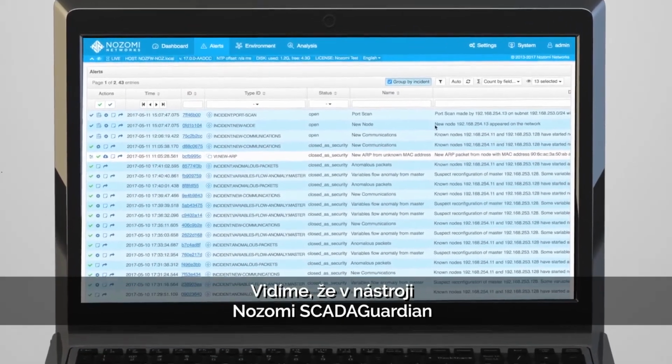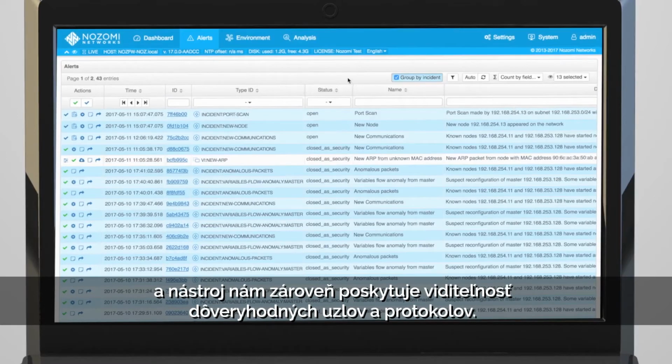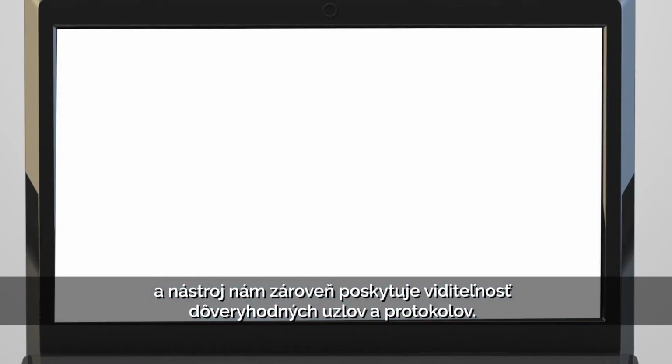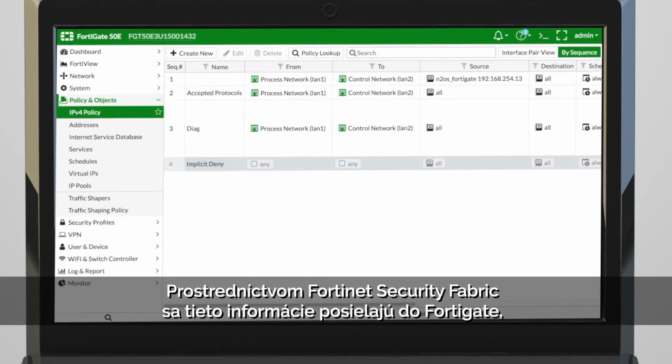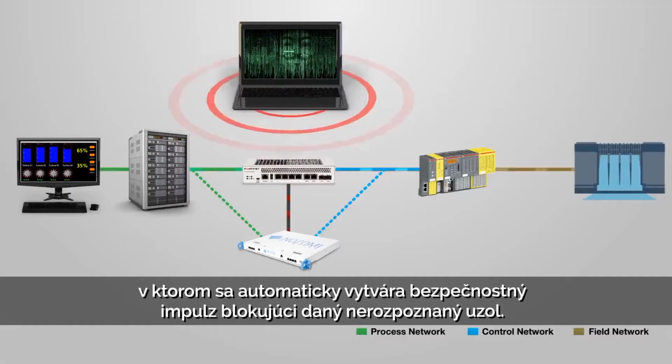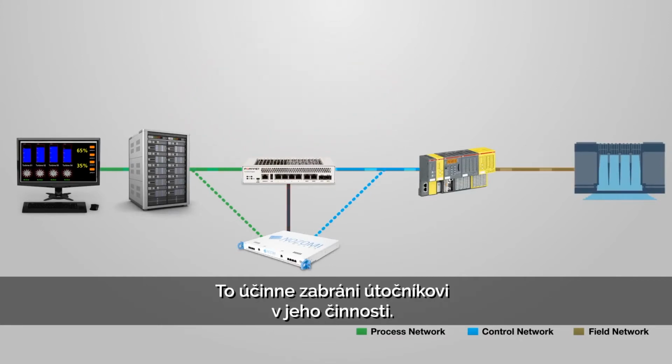This would normally result in the attacker discovering potential vulnerabilities. We can see that the Nozomi SCADA Guardian has a new alert identifying the unrecognized machine in the network, providing us with the visibility of trusted nodes and protocols. Leveraging the Fortinet security fabric, this information is sent over to the Fortigate, in which a security policy is automatically created which has blocked the unrecognized node in question. This has effectively stopped the attacker in his tracks.